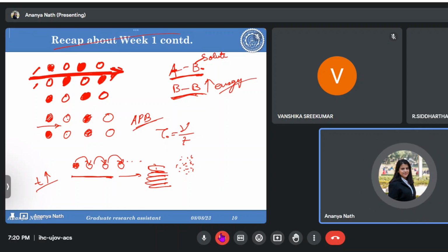Also, the mobility of the dislocation is equivalent to the motion of the dislocation. And we are just trying to restrict this mobility of the dislocation, and also trying to restrict the path of the dislocation so that it finds it difficult and needs more stress or energy to break the barrier.